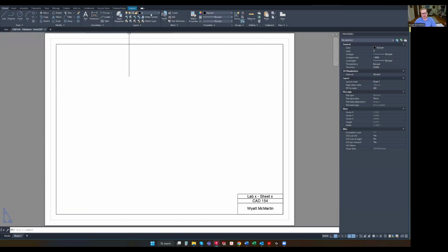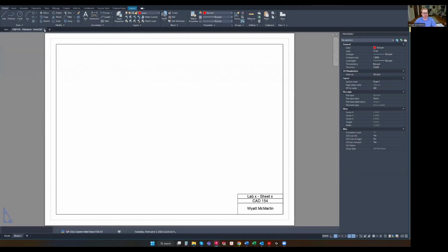And now to double check that we have all of our layers set up properly, the drop down under layers should now contain all of the different layers that you just created. And before we save and close, just make lines the default layer, click Control S, and go ahead and click the X to close your title block.